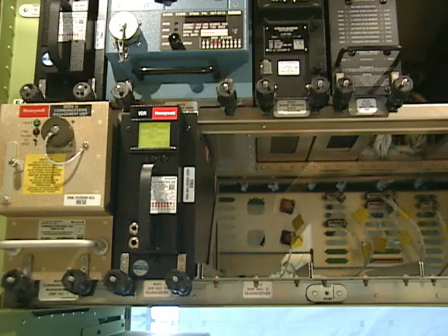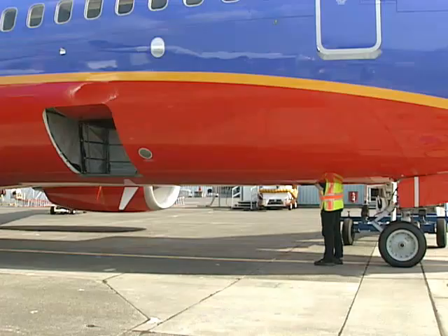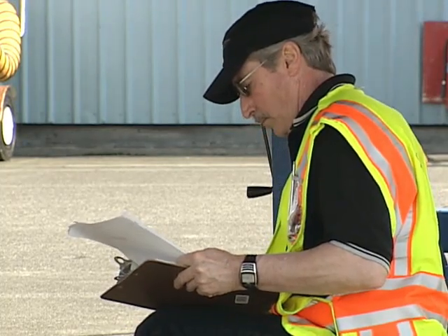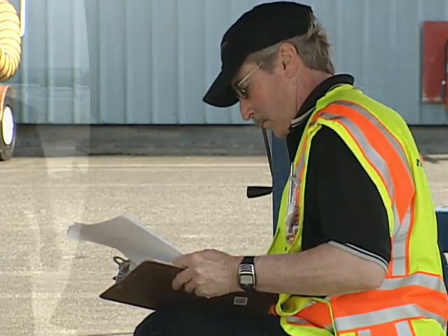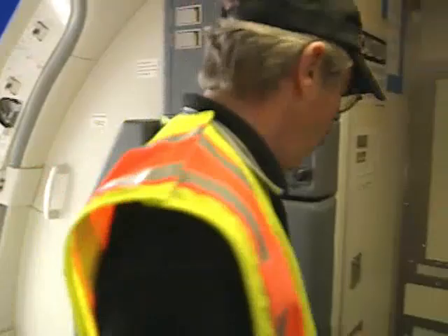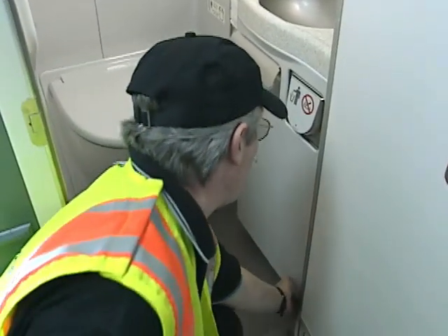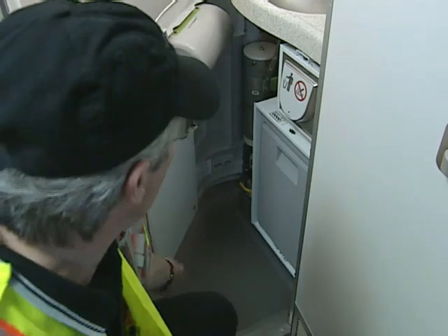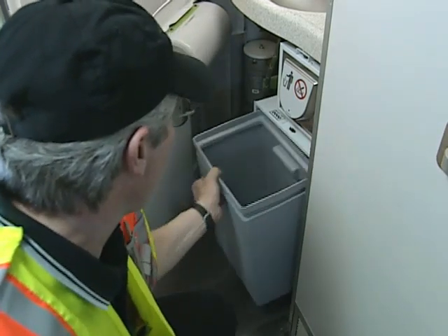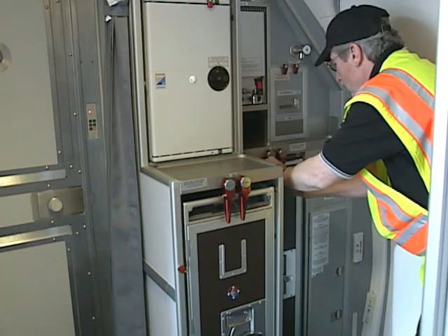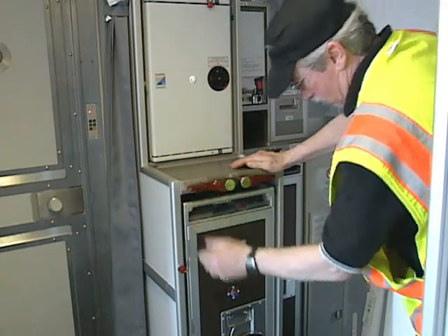Here's an example of something that needs to be removed. Next, check the E&E bay. Here's an example of something that's missing. Normally we would replace the missing item, but this component is out of service and will not be returned prior to weighing. So we need to document its weight and normal location.